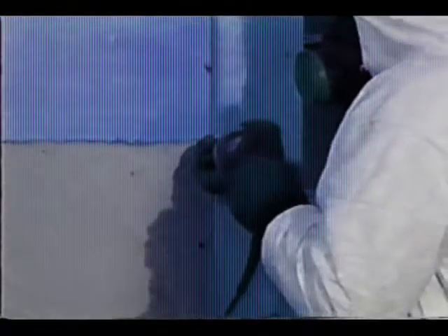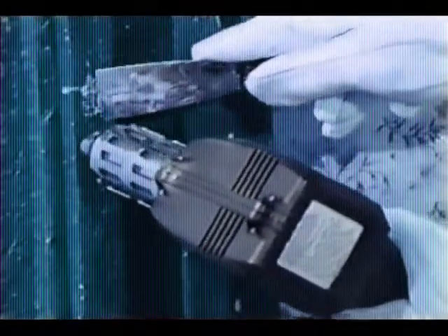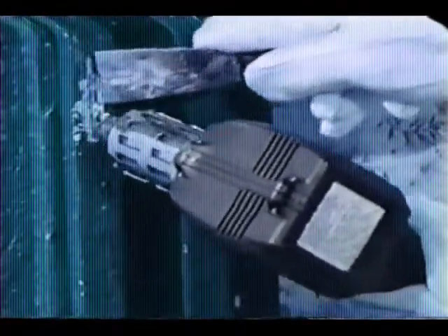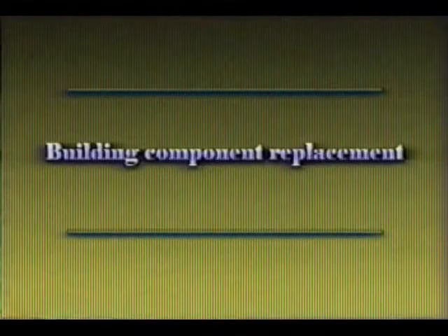Abatement involves lead hazard control treatments that are designed to last at least 20 years. A contractor certified in lead abatement is required when abatement is conducted. Abatement measures include building component replacement, enclosure, paint removal with chemical or contained abrasive, and encapsulation.